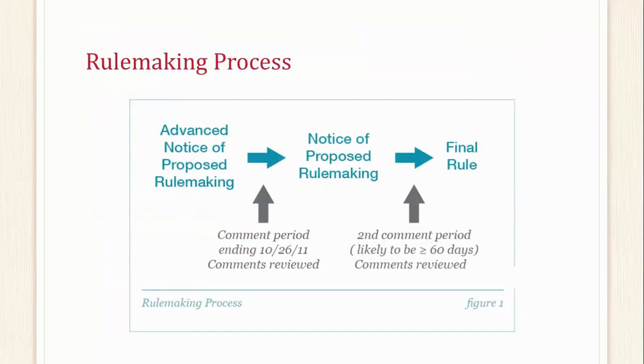A good example of that is one that really kind of struck me kind of weird, the ability to lay plastic on top of the ground temporarily up to 2 years. I thought it was just really strange. I could see you using a temporary bypass or something like that, but not on top of the ground for 2 years. Come to find out, in Alaska, whenever they go to install services during the wintertime, it takes 8 hours to dig 6 inches. Okay? 8 hours. Propane, it looks kind of like a square rack, and they put it on the ground, and it takes them 8 hours to dig 6 inches. So it's not feasible for them to run services underground during the wintertime. So what they do is they lay the services on top of the ground, and when the summertime comes around, they dig down and they bury the service line. So things like that we have to take into consideration whenever we're writing these.